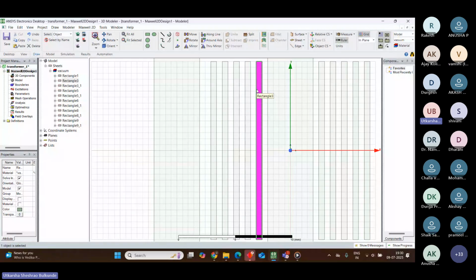If you had just duplicated it, you wouldn't need to change that for every winding, because in duplication, whatever happens to this winding will happen to the other winding also. But in copy and paste, it is not the case. It is just for your convenience, a one-time thing. For now, it will look the same, but if you change the parameters of the original winding, the copied parameters will not change. Understood? The difference between copy and paste and duplicate.